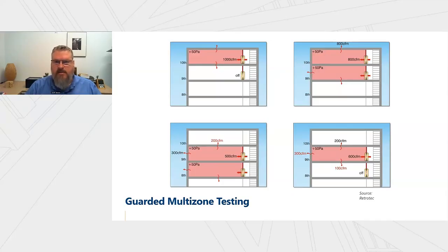What that's going to do is zero out the leakage across there, and whatever that top fan's delivered air volume drops by, you can essentially subtract that out as the floor leakage, and you now have just the exterior boundaries that you're trying to measure.